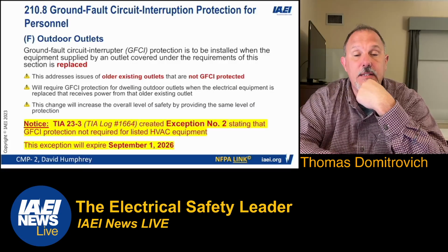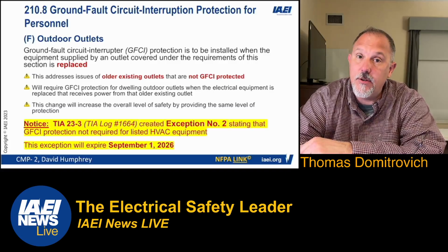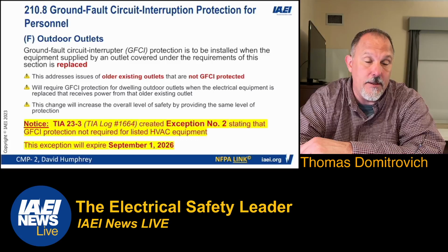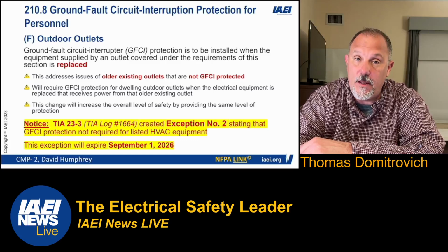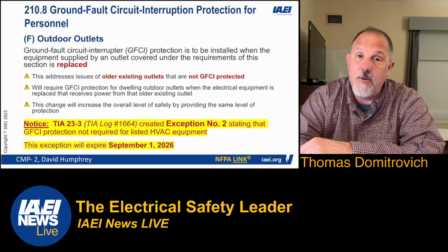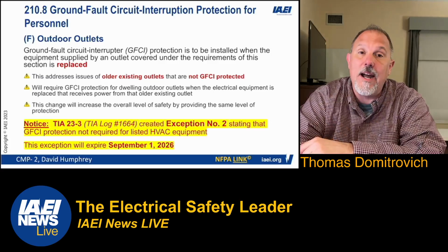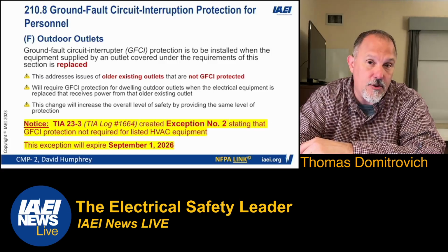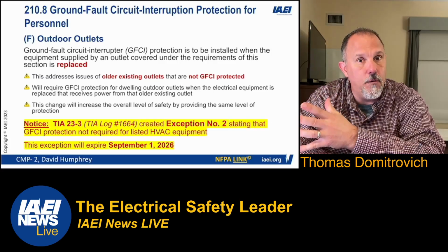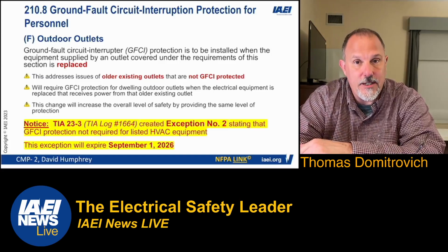There is HVAC equipment that is using the equipment grounding conductor as a current return path for single phase loads within the HVAC equipment. Violates Article 250. It's permitted by the standards. There's also HVAC equipment that is using drive technology, variable frequency drive technology, and higher frequency leakage currents are coming back over the equipment grounding conductor and causing GFCIs to trip.